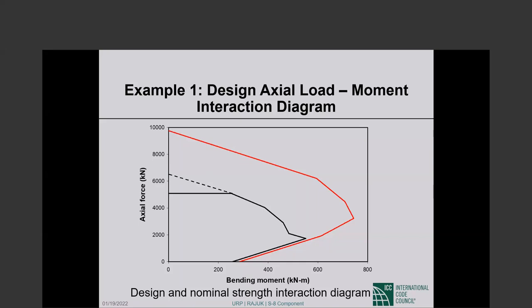It is not that you will never use spirals in a square column, but it is very, very seldom. The spirals are almost invariably used in circular columns. But I said that the circular columns themselves are relatively rare in buildings other than parking structures. So we don't have a lot of spiral usage in buildings other than parking structures. That's what I was trying to say.